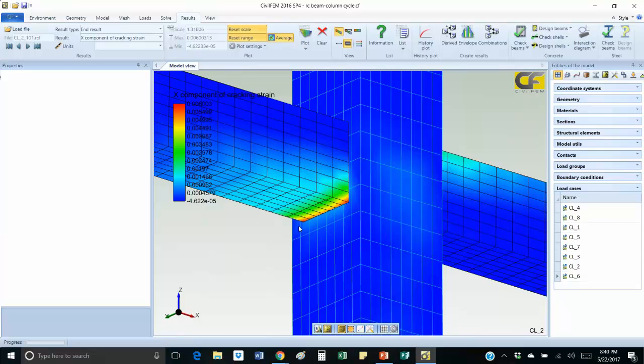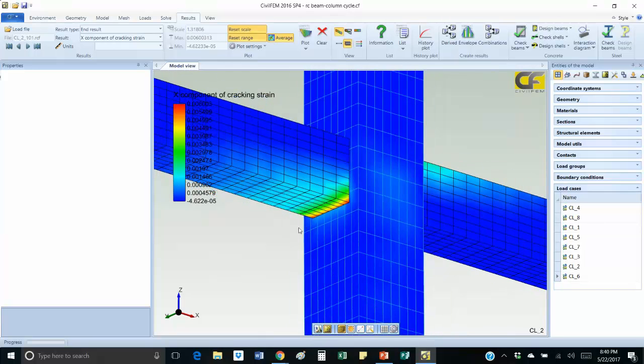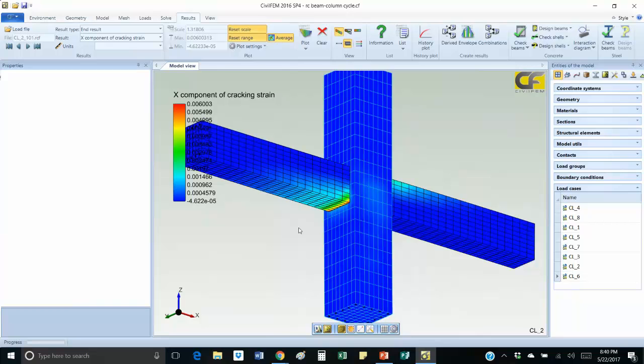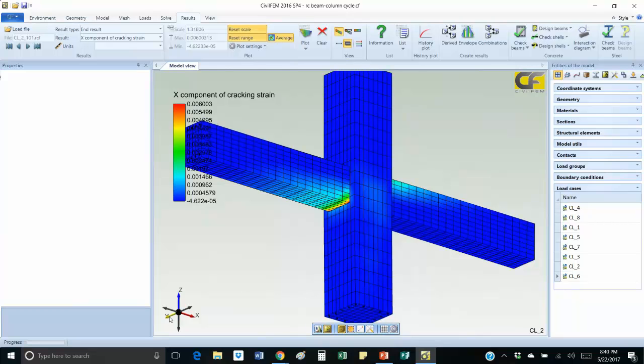And the advantage here is that we can reproduce our models for calibrating whatever other model we have. If we have tested and calibrated this model with a real test, we can easily use this model for calibrating another behavior, such as plastic hinges, fiber elements, or hinges with defined lengths, whatever model we're going to use.